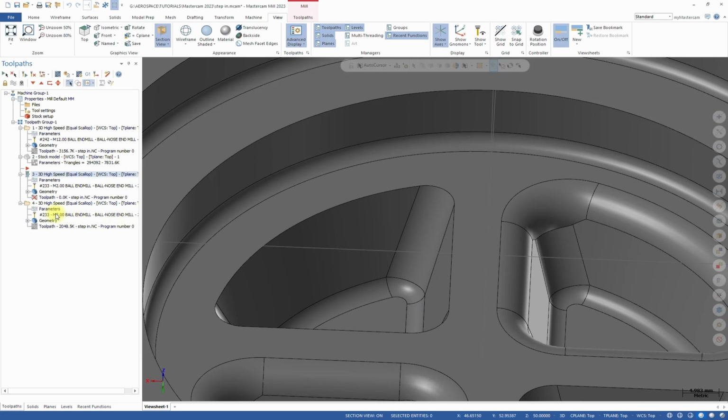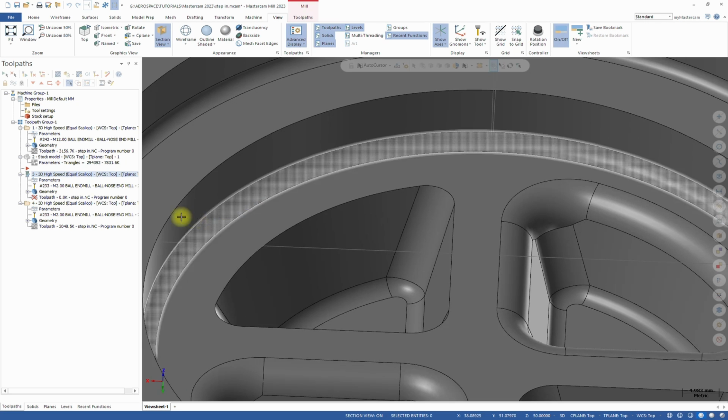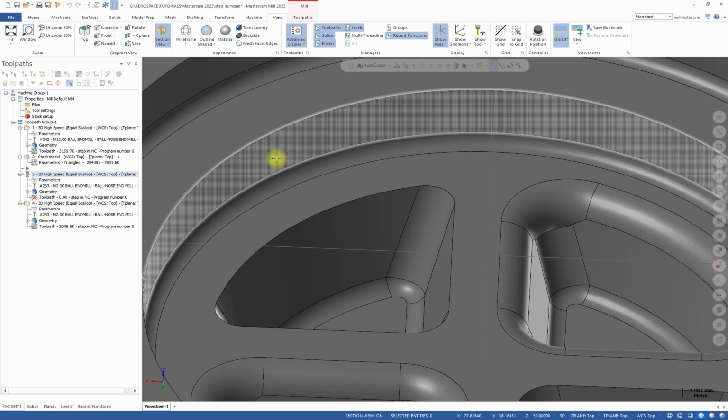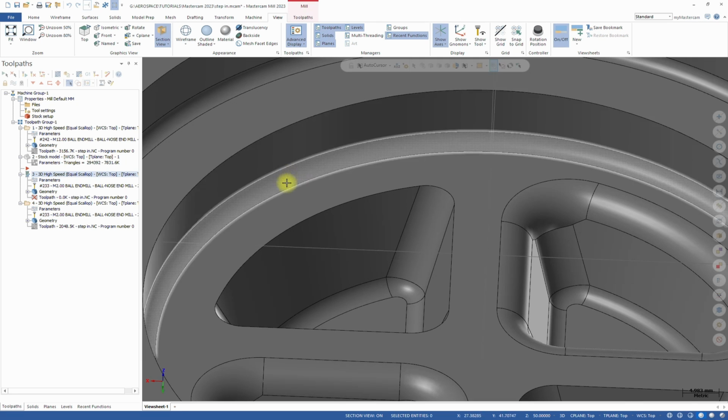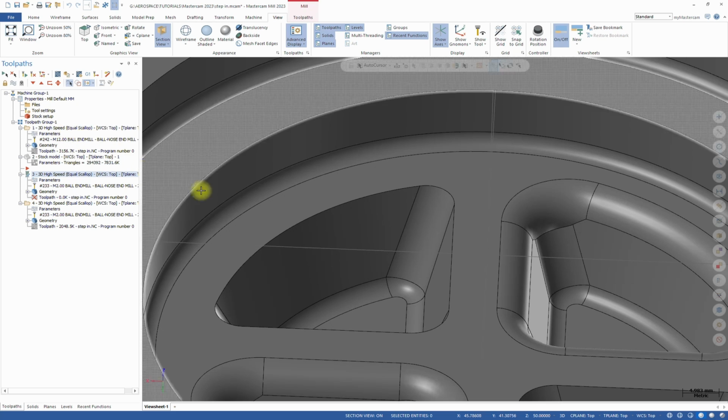In this way, when we will be using this tool here, it won't hit this thick layer of material. So we will have a set of 1 operation and then copy that twice, do some minor changes, and I've got finishing with the bigger tool, then pre-finishing and finish the rest area, okay? The area that was left behind this tool.